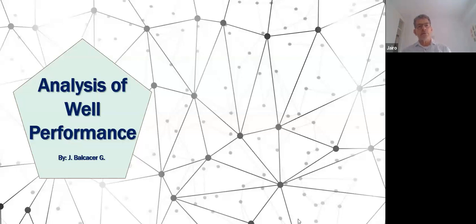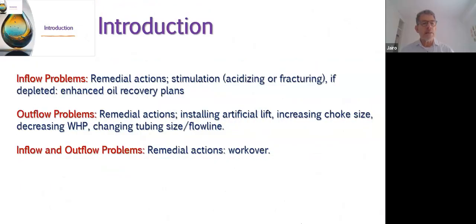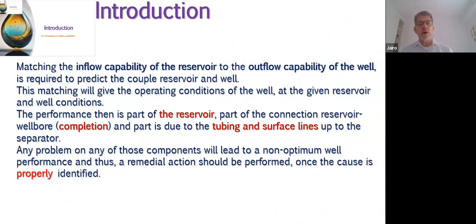When you get those two, basically it's wellbore performance analysis, what is commonly called, using a trademark, Nodal Analysis. Basically, matching the inflow capability of the reservoir to the outflow capability of the well is, of course, a requirement to predict the coupled reservoir and wellbore.